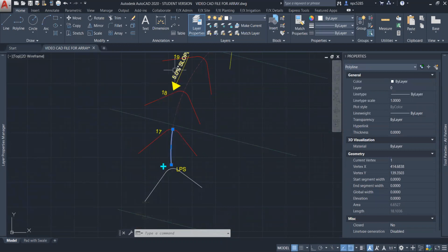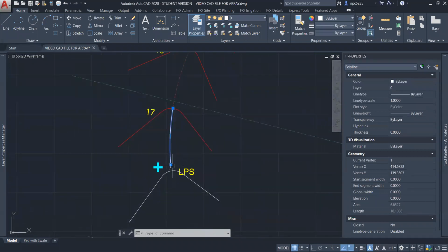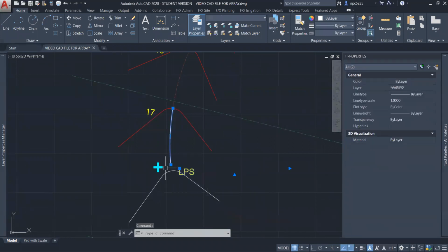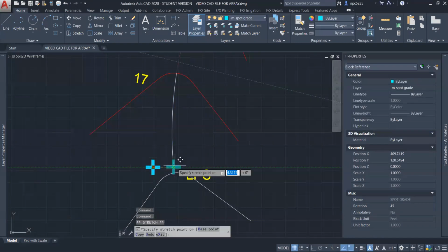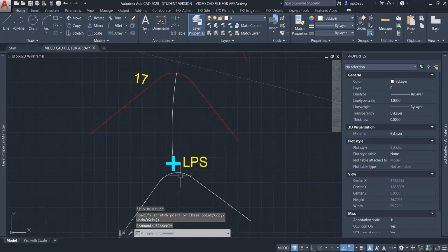And I would multiply that by my percent of slope, 0.05, in order to acquire your V, your vertical change or your rise. That would tell you what to subtract from 17 to determine exactly what this point would be, rather than going all the way down to the whole number. It depends on how much space you have in your drawings and things like that, on which method is the best to go about it.